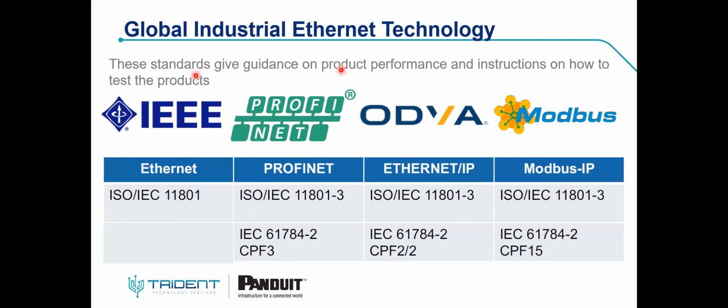All these communication protocols are designed for industrial environment usage for automation, as we said, real-time monitoring and control. You need to know that all network components designed for the industrial network need to sustain vibrations, heat, electromagnetic noise, and any other industrial conditions.